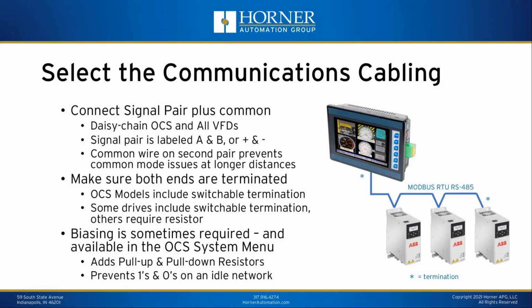You need to make sure, whether it's just two devices or four, like I've shown here, or even more, the devices on the end of the network should be terminated. Now, if the OCS is at one end of the network, then the OCS has the ability for doing termination outside of the cable.